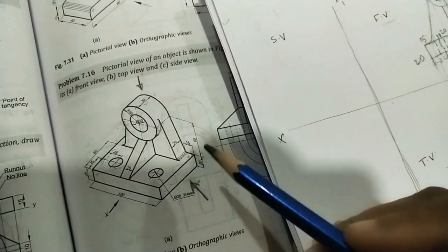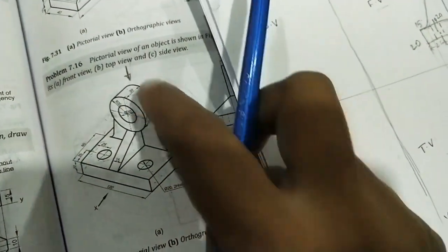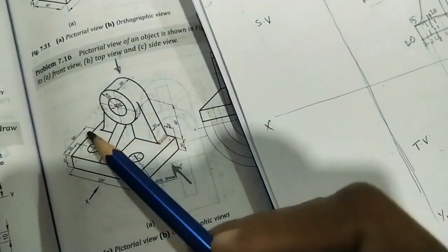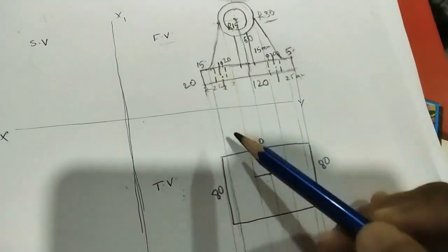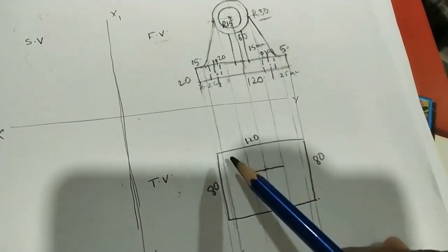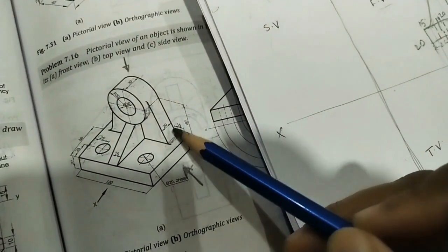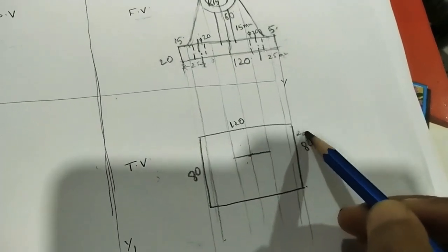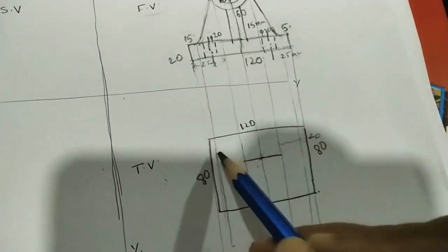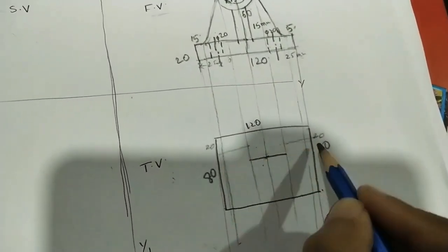Here from the top we can see these 20 mm boxes at both sides. Actually these are slope lines, but from the top they look like rectangles. But here a gap is there, 15 mm this side and 15 mm this side. Let us take that gap of 15 mm. Already we took projectile lines at 15 mm. This is one projectile line, this is another projectile line, this is 15 mm, this is 15 mm. After that mark this 20 mm thickness. From this corner take 20 mm, here 20 mm lines like this. This is 20 mm, this is 20 mm. So here the gap is there, 15 mm, 15 mm.